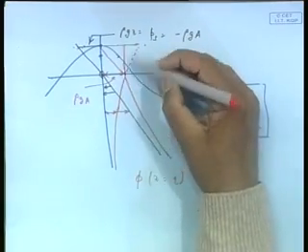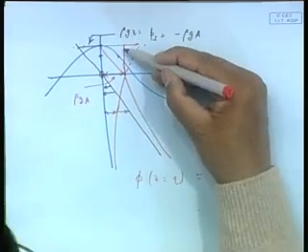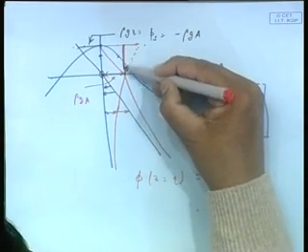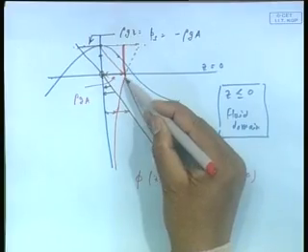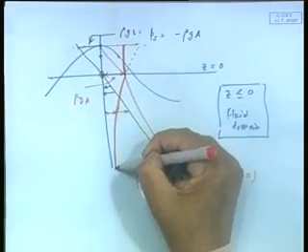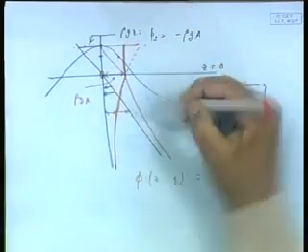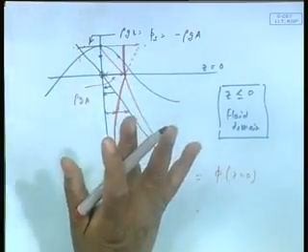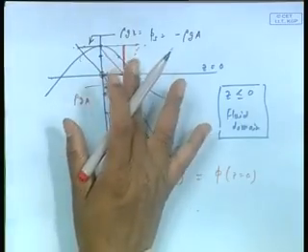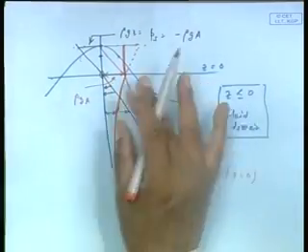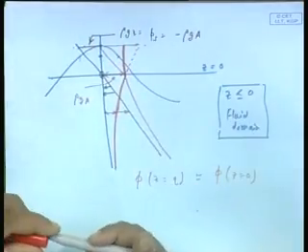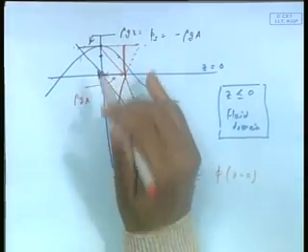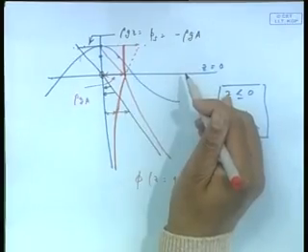Now, this is extremely important for us to understand, because you must have a physical pressure here, and the dynamic pressure is varying like this. Once again I will repeat this, whereas hydrostatic pressure is varying like that. Now, if I were to evaluate a pressure in this regime or anywhere under a wave, you cannot use hydrostatic pressure by itself, because if you did that you end up getting a wrong result. You have to use hydrostatic and hydrodynamic pressure simultaneously.